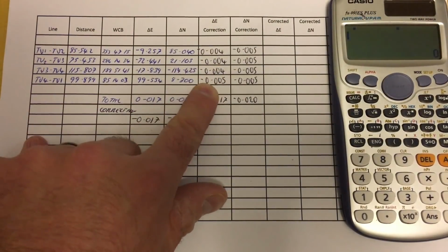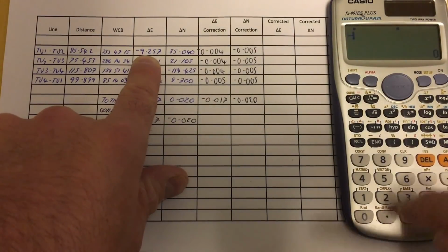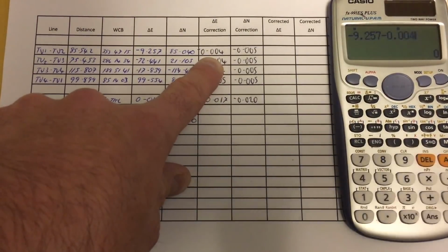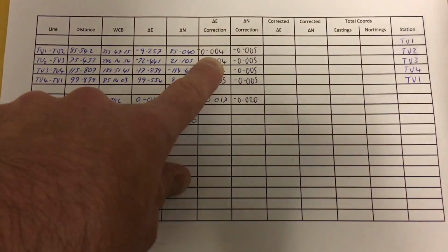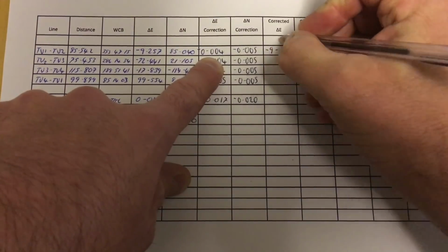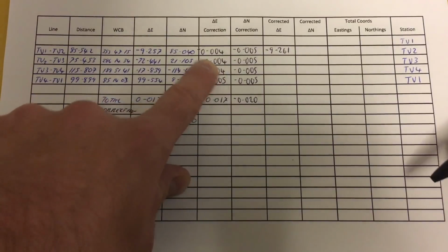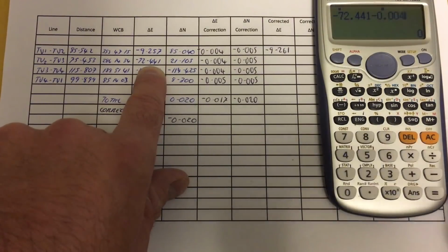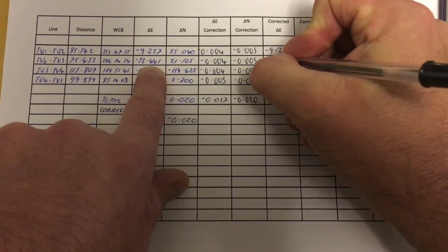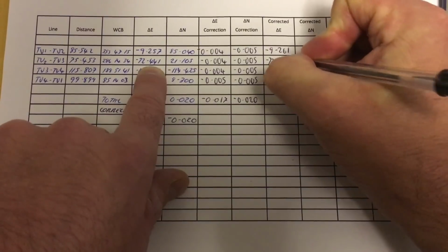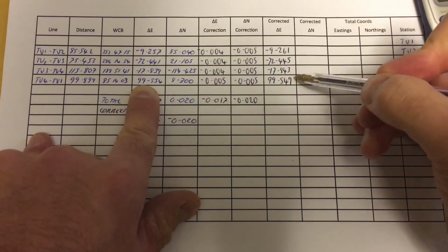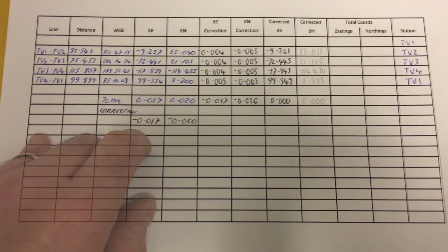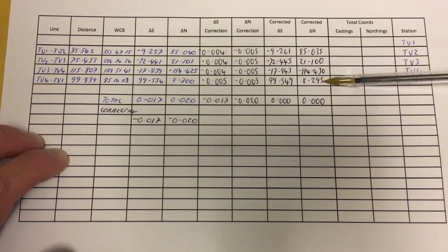It is now necessary to start applying those corrections to your original calculated Delta Eastings and Delta Northings. Remember to take care during this process, as it is easy to mix up the numbers in the different columns. I prefer to calculate all of the corrected Delta Eastings to begin with. However, the choice is yours. In order to check your calculations, the corrections of each Delta Eastings and Delta Northings should be summed. They are only acceptable if 0 has been achieved.